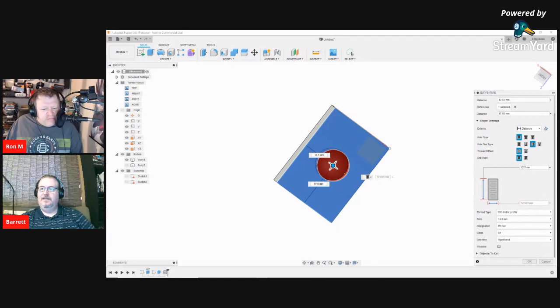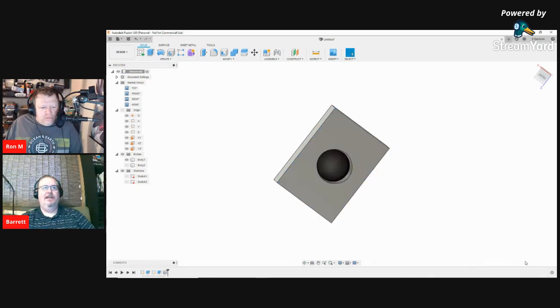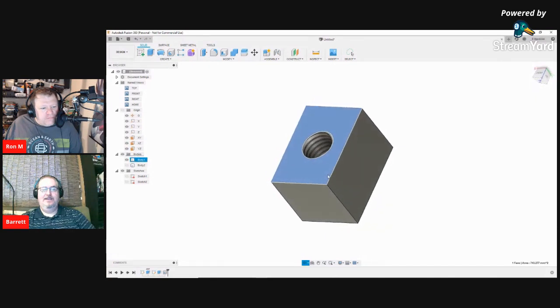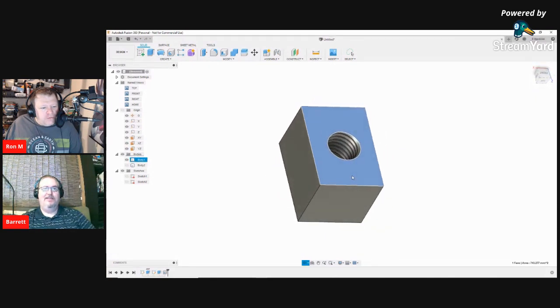There it is. See the modeled button? There's a little modeled radio button. Yeah, I do see a check box. Check that, and then click OK. And then it will actually physically model. So now you're going to see a difference in what those threads look like when you look at them. Before it looked a little bit like a picture. Now those are actually modeled threads.